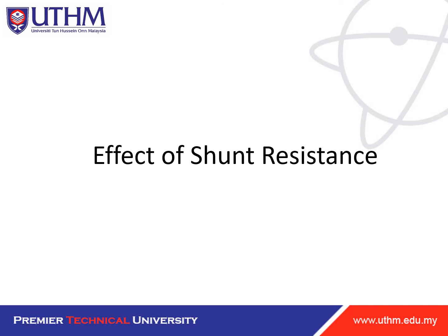Then, the effect of a shunt resistance is particularly serious at low light levels, since there will be less light-generated current at lower voltage, where the effective resistance of the solar cell is high. The impact of a resistance in parallel is large.